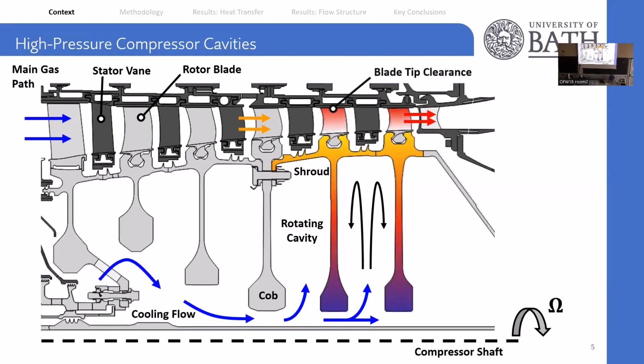At later stages, the temperature gradients through the disk can result in thermal expansion, which can affect the tip clearance of the blades. As we approach future aircraft engines, with higher overall pressure ratios, the sensitivity of this tip clearance increases as the size of these cores shrink. For gas turbine designers, a complete understanding of the temperature and this radial growth is essential when designing new engines. My work covers a new conjugate methodology to help understand this.